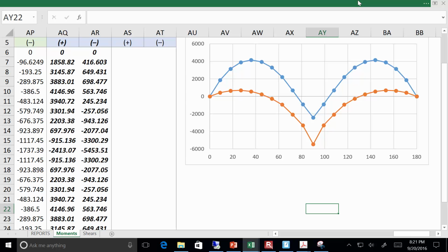So the next step, I know it's taken 4 or 5 weeks to do one step of this problem, but the second step would be to say, all right, here is this beam, what is its moment capacity? Is it strong enough to resist these moments? For instance, right here, I have a range of moments from around 500 foot-kips to like 4,000 foot-kips. So obviously the 4,000 is what governs.